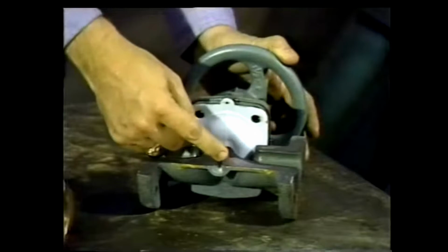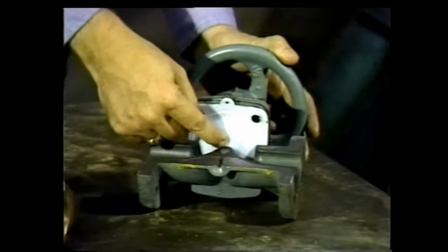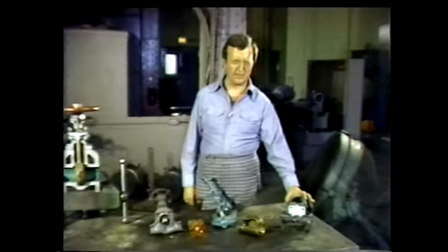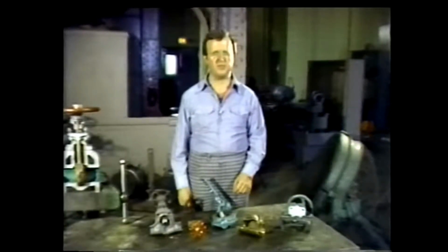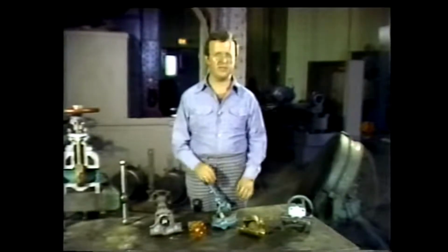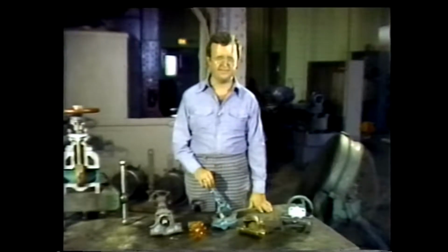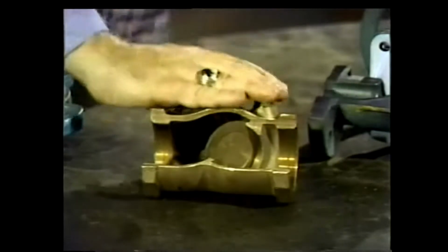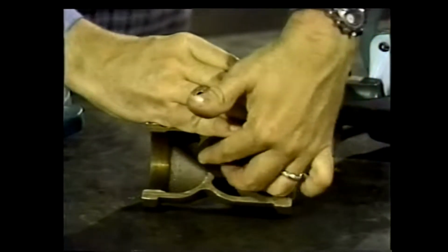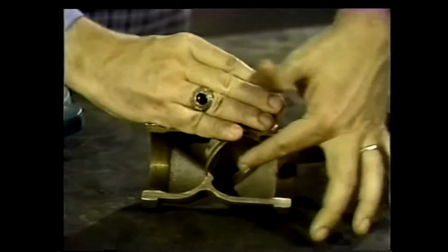In a diaphragm valve, the disc is made of flexible material, such as rubber or plastic, to provide a seal that prevents leakage into other working parts of the valve. These valves are most often found in systems with a flow of chemical fluids or harmful gases, where any leakage could be potentially dangerous. Finally, we'll look at a check valve. Now, these valves are used to allow the flow to go in one direction.